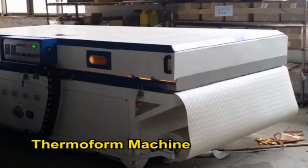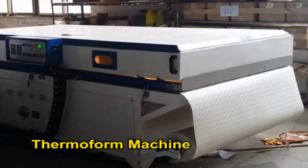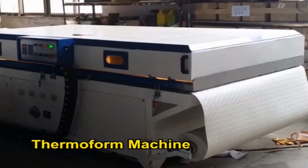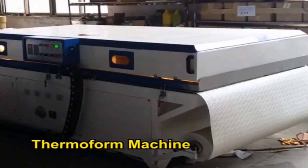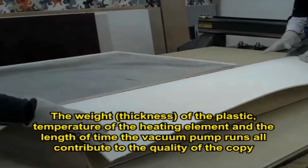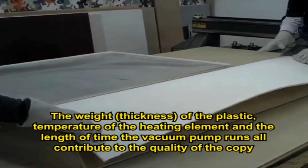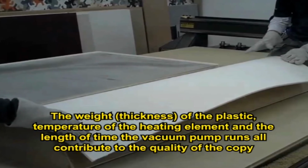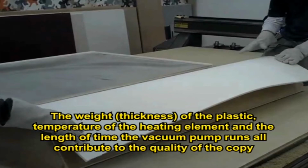A thermoform machine is the most accurate way to produce braille text and tactile graphics. Research indicates that vacuum form graphics generally provide a higher level of readability than other techniques. Let us look into some considerations that should be kept in mind before creating vacuum form tactile graphics. The weight of the plastic, temperature of the heating element and the length of time the vacuum pump runs all contribute to the quality of the copy.